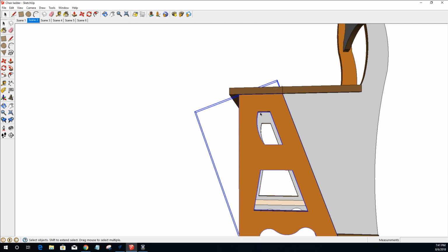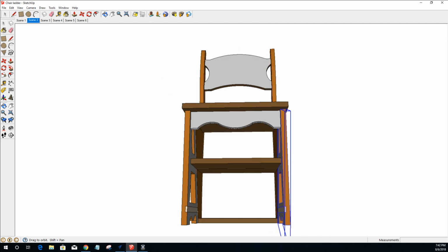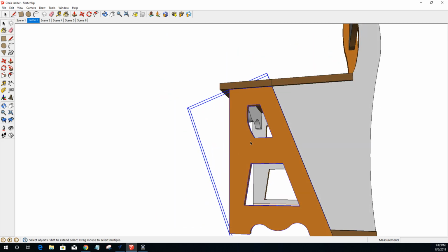Now, if I were cutting this on the back side, if we pop back over to the Vectric here, that shelf groove, where that dado is, is only 1/4 inch deep. So I have a 1/2 inch of material here. If I was doing some type of 3D carving, heck, if I was really creative, I could make it to where this whole side here was some sort of 3D carving, not going any deeper than a 1/2 inch, so it'd be a very shallow 3D carving.